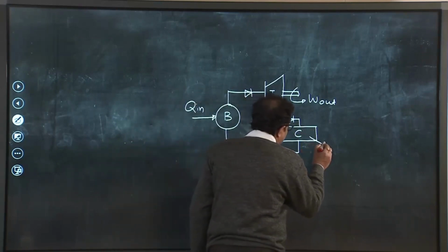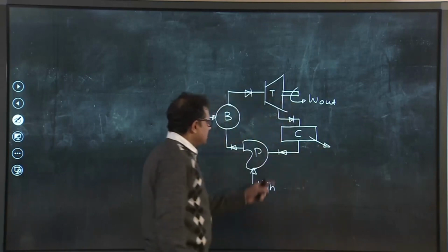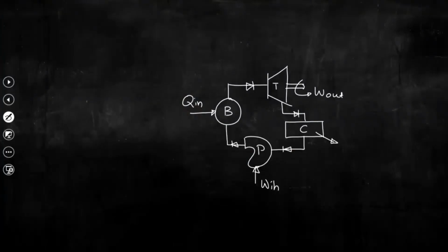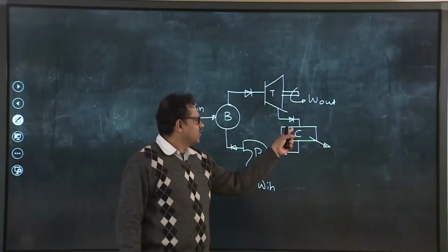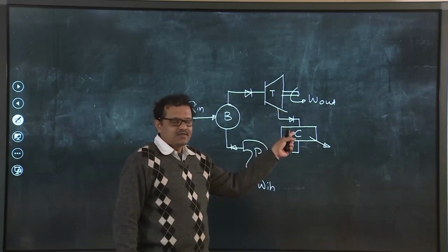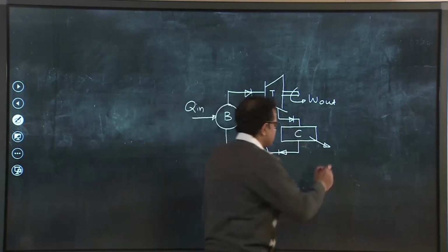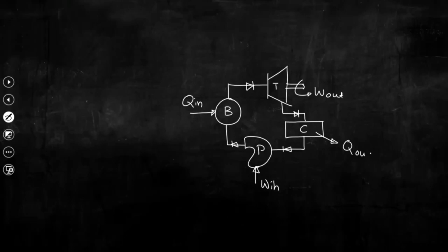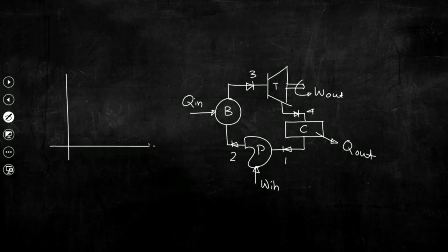Now, this particular place, that is the condenser, wherein exit steam of the turbine is taken, that steam releases heat and gets converted into water, and that water is pumped back to the boiler. So, now we try to draw all these processes in this TS plane.